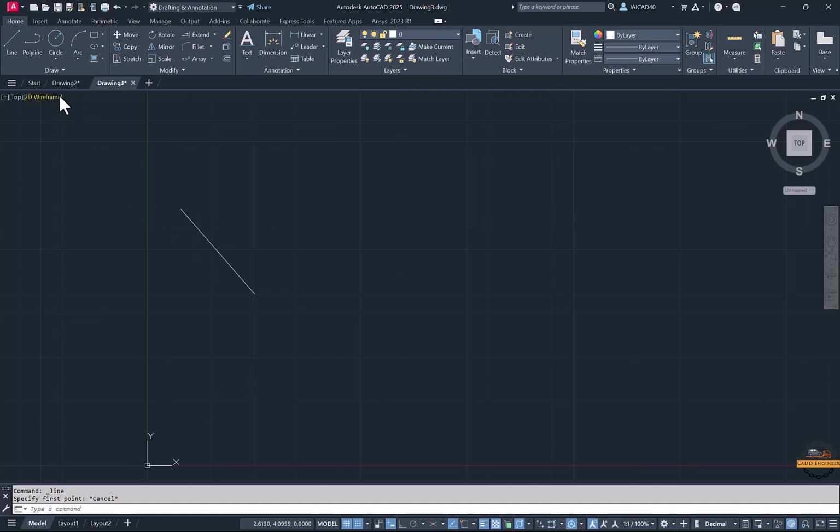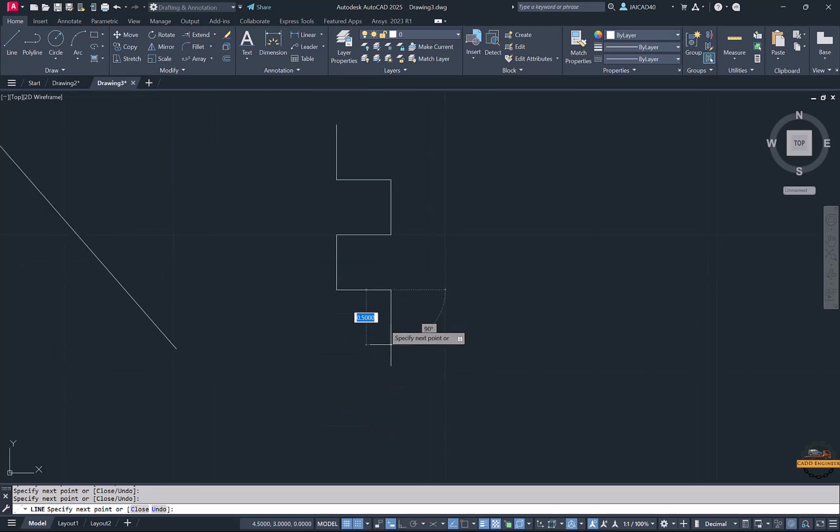The F9 key is for picking the grid boxes. You can see that my cursor is sticking to the grids, so it picks the grid boxes. If you have specified any size of grid, you can pick those grid boxes and draw the object with their help. Like this, I am making a 0.5 size grid box.